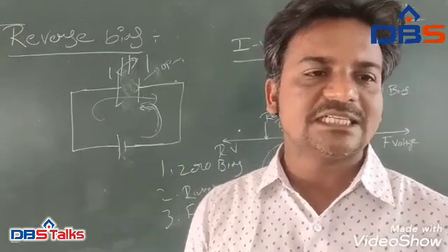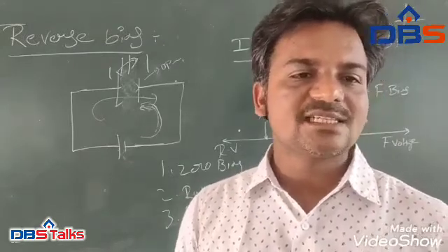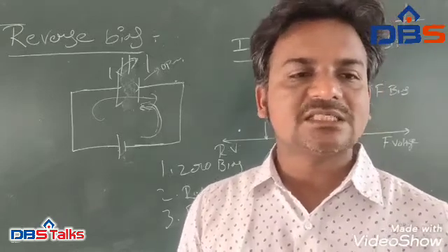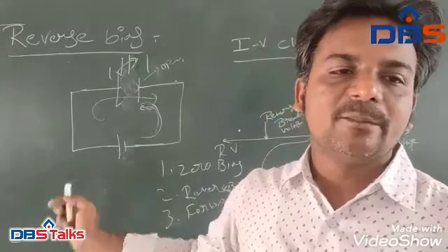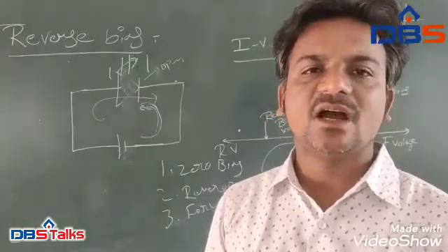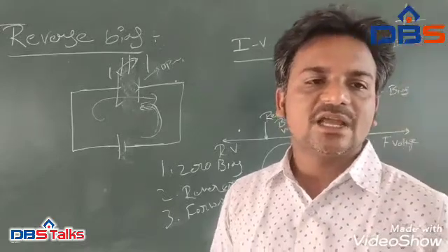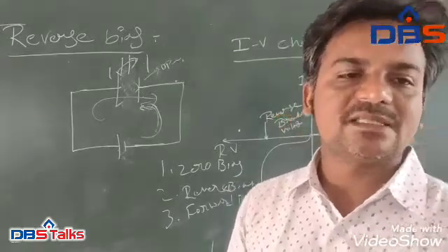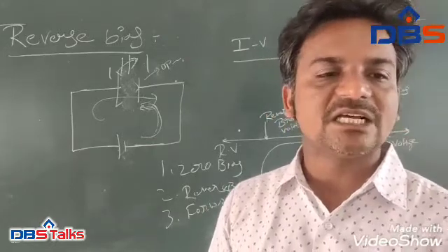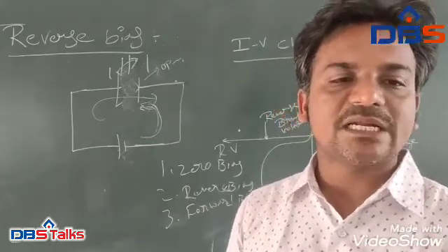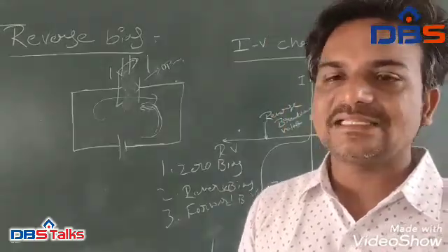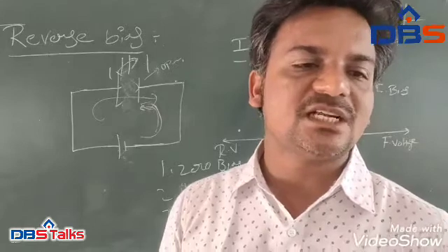In a zero bias junction diode, no external potential energy is applied to the PN junction. However, if the diode terminals are shorted together, a few holes, the majority carriers in the P-type material with enough energy to overcome the potential barrier, will move across the junction against this barrier potential.